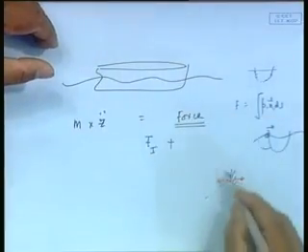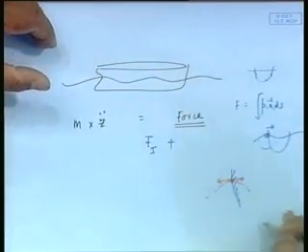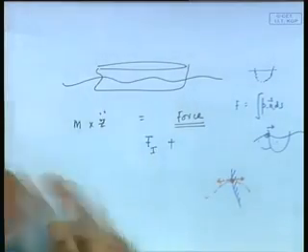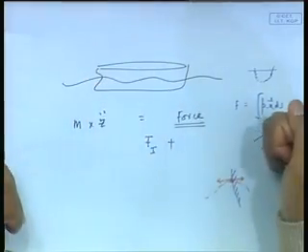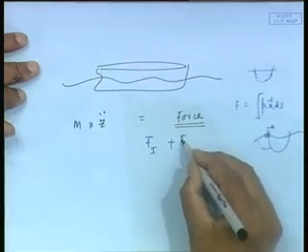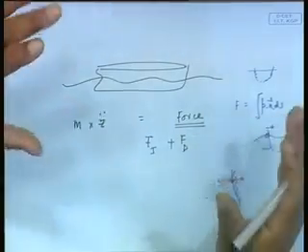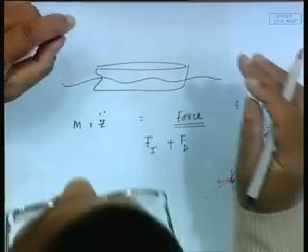So now that wave obviously would have altered the pressure field, because the pressure is now no longer d phi I by dt, because there is another phi. So we call it the diffracted force. Remember, in this there are again two scenarios. I presume that I have held the body fixed, I did not allow it to move. I kept it, somebody is holding it by hand, wave comes, the particle cannot move, so it must have created a wave back. This is one part, and obviously it will add up to one force. We call this FD, the diffracted force, similar to reflection, but there is more to the story.